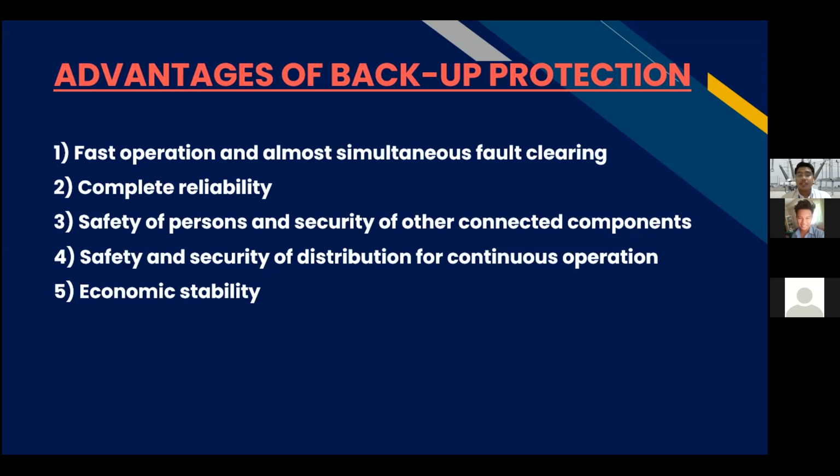We have a lot of advantages in using backup protection, but let me end with the most important advantage, which is economic stability. All the advantages are linked to this advantage because if the power system operation stops, the effect will be like a capillary effect, and the operations of the users will also stop and end in economic losses. But because of backup protection, the operation stoppage will be lessened to the least possibility, and it will continuously operate even if the other components have a problem.